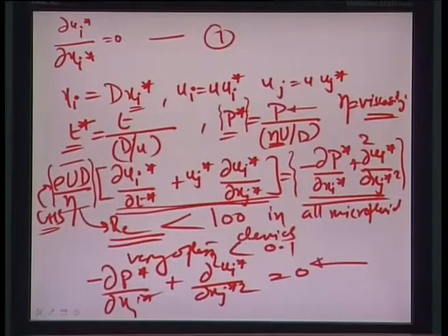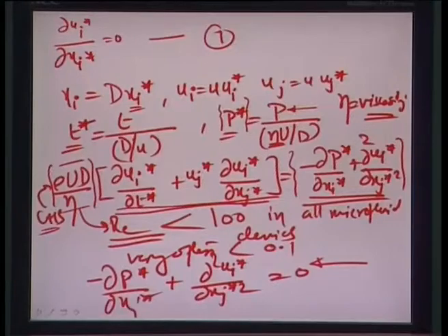One conclusion which almost always comes out is that at this particular scale the momentum equation becomes time independent. Therefore it is almost always obvious to assume that if you have two or three flows introduced into the same micro channel, and we assume a low value of Reynolds number, due to which the left hand side of this momentum equation becomes 0, the obvious conclusion would be that the flow is pressure driven, number one, and number two, that it is time independent.